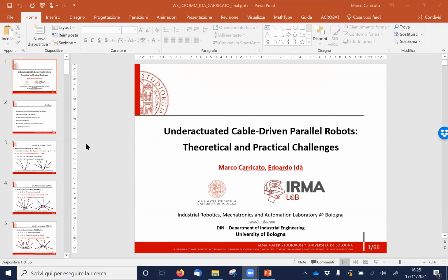Then you can measure, of course, the tension, as many of you do, which provides another very useful piece of information. But tension information is not necessarily very clean, and also depends on which part of your system you implement your force sensors.